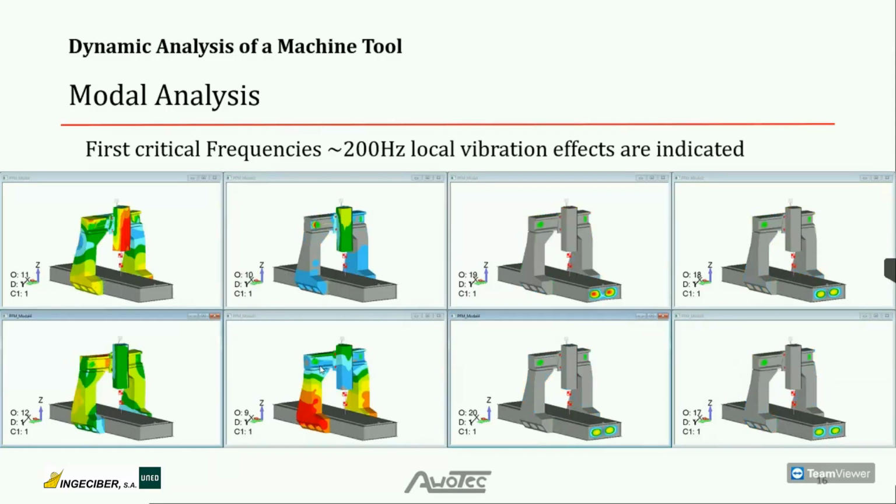Okay, the eigenvectors which are shown here in the color plot are related to the z-axis, to the portal itself, and so on. But it also can be seen that from 200 Hertz up, the eigenmodes are related to plates that are located somewhere in the mainframe, the stiffener panels, and are not related to large masses on the structure.